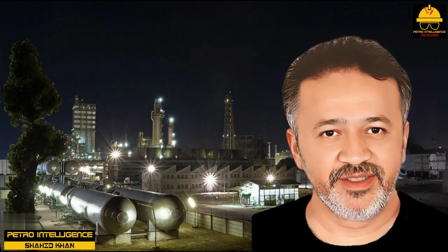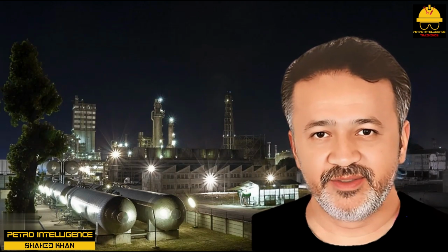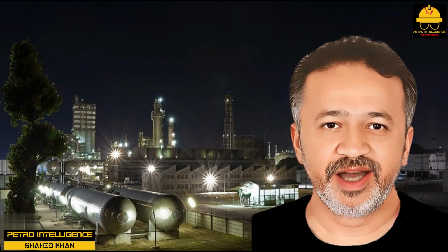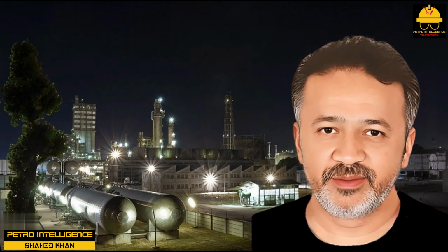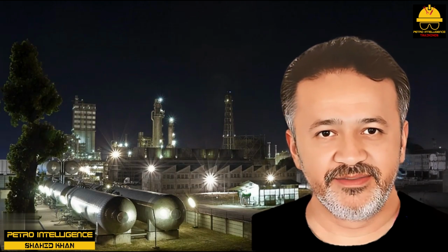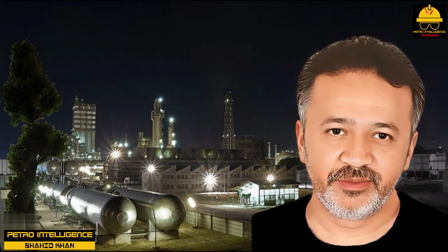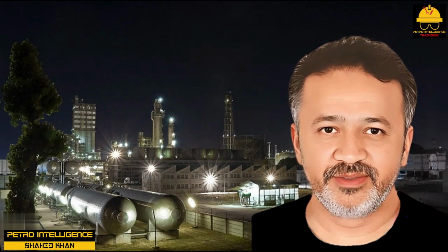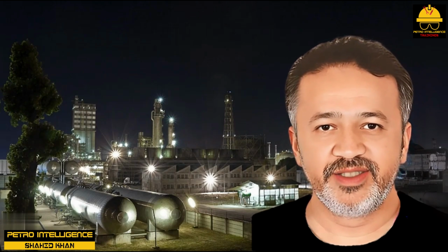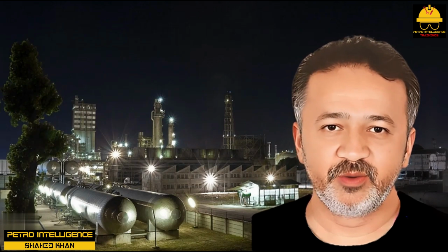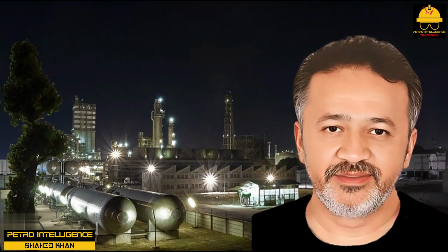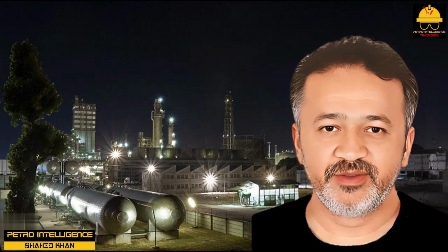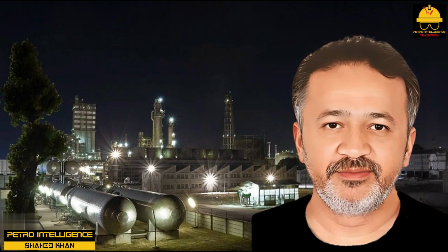But it also increases the rate at which coke deposits on the surface of the catalyst, which is bad. The extra coke blinds off more catalyst area. The reaction rate drops. More sulfur is left in the diesel. The operator increases the reactor temperature to speed up the reaction, which leaves more coke on the catalyst. When this game is over, we are at the end of run condition.